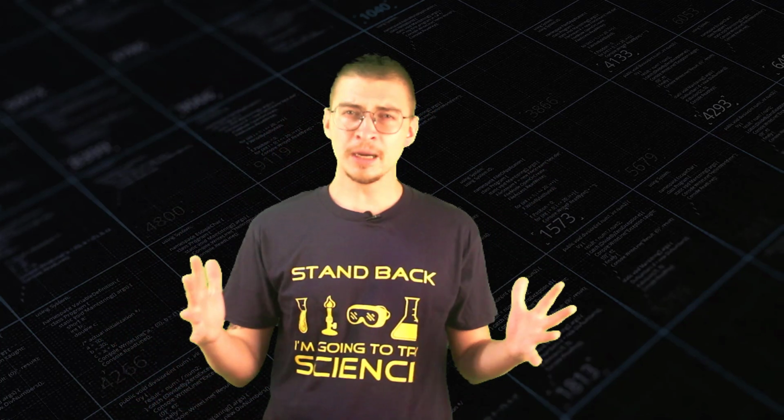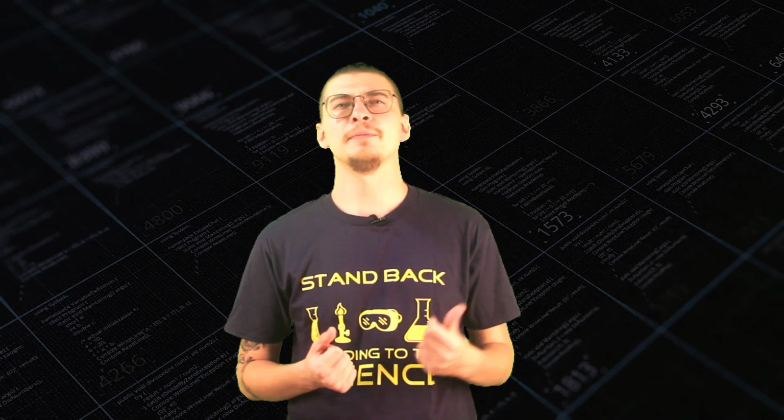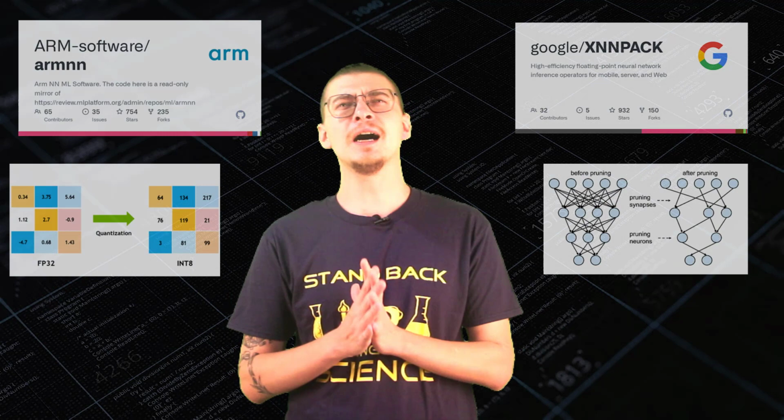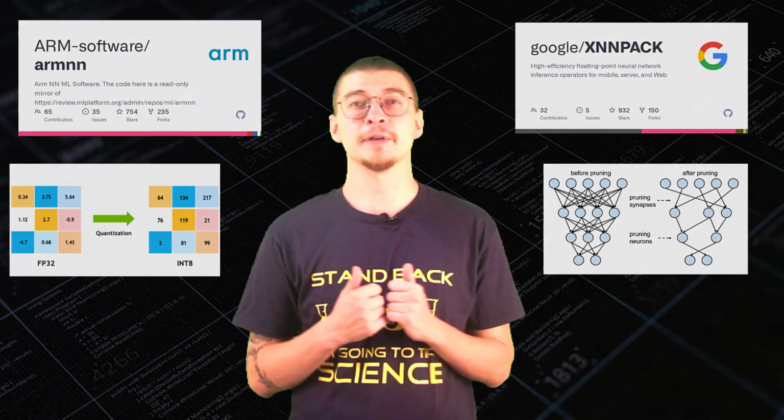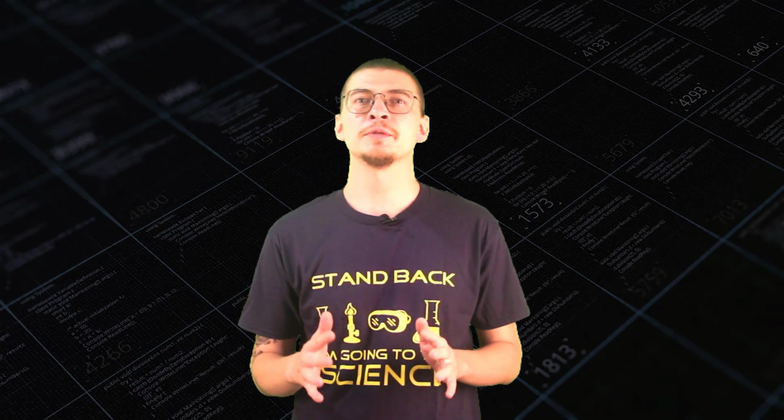So to summarize all of that, the fact that the board does not have dedicated hardware to accelerate neural network inference does not mean it's useless for machine learning. There are some optimization options that allow achieving acceptable inference speeds. Applying some of these techniques, such as optimized kernels, can be a bit tricky though, and requires some tweaks to the model architecture and possibly compiling the inference optimization packages from source, since a lot of optimizations are currently on the bleeding edge of development.